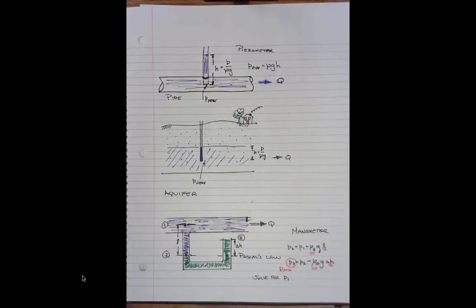So the manometers are connected to a fluid. They have their own working fluid. They measure force differential between the fluid and the atmosphere. And the devices are all assumed to measure centerline pressure, which probably in a moving fluid like I have drawn here is pretty reasonable. As with all the other devices, that force per unit area gets equated to the column height through the hydrostatic pressure equation, P over rho G equals H.